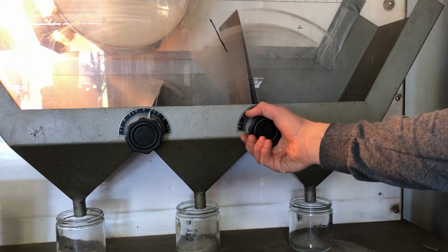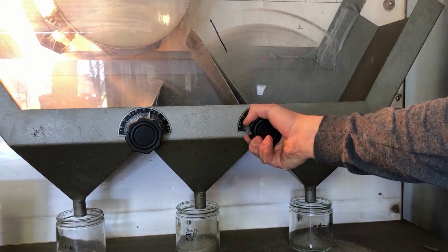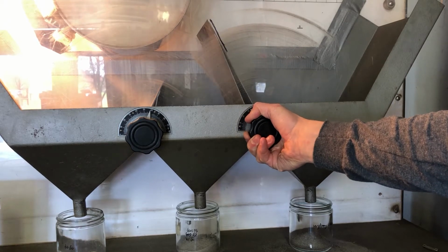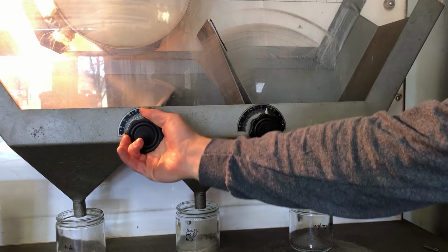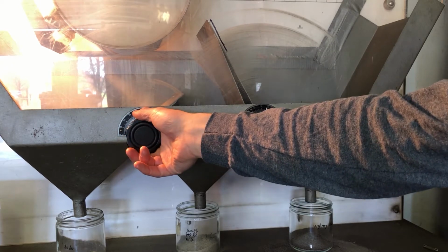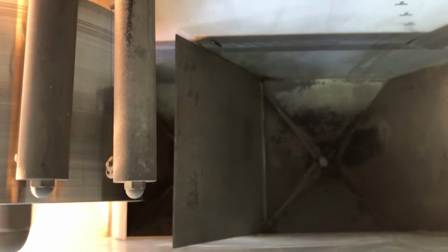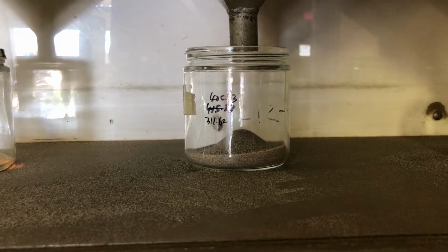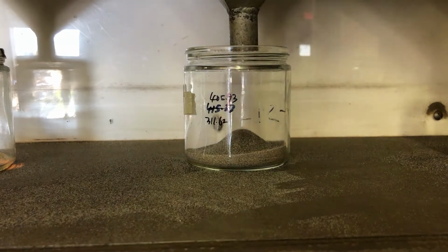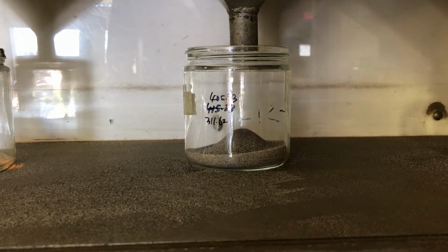Splitters at the bottom of the device allow the operator to select where they want to make the split according to trajectory. Of course, the process is not perfect, and some titanium particles get pinned to the rotor, and some gangue particles get thrown. At the bottom of the device, 3 funnels collect concentrate, tailings, and middlings products. In this lab, I'm going to combine the tailings and the middlings into one tailings product.